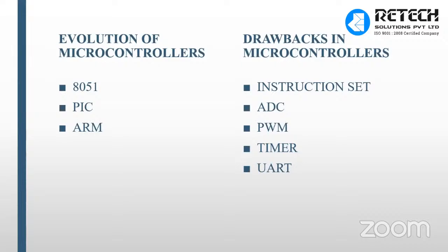But unfortunately, the 8051 does not have inbuilt PWM pins. But Arduino has 6 PWM pins. Via those pins, we can easily control any motor. We can control a DC motor or stepper motor using those pins because they have an inbuilt PWM function.